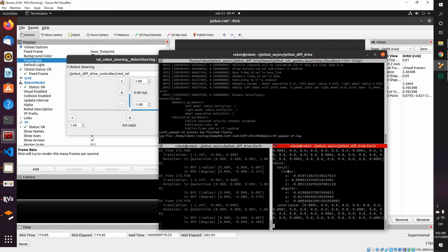I'm not saying that the author of the plugin that I'm using is odd. It's all about my model, and something is wrong there. So my workaround will be to make a node to check the transformation between the base link and the base footprint. That's my way to check that.